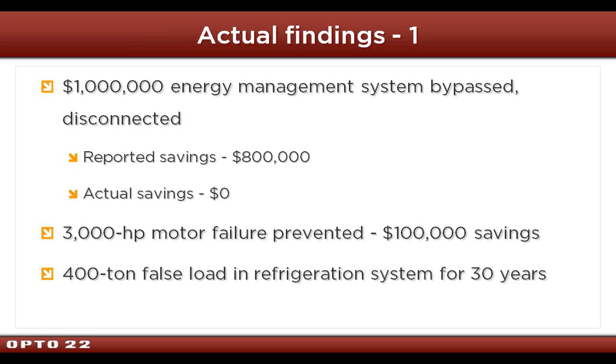So that's what you get without data and without actual management. I got a letter from Cosmos Cement Plant outside of Louisville, south of Louisville. Our data showed rising amperage on a 3,000 horse motor. He said they shut it down. It would have been a catastrophic failure. They avoided $100,000 in repair in one day from that data.